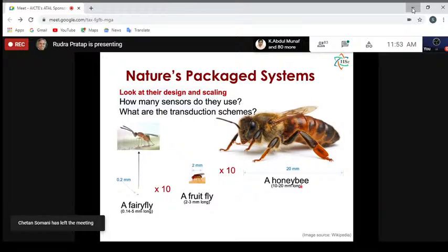On top of that, let's do a photoresist coating. Photoresist, as you know, is a polymeric material. In solution form, you can easily drop it and spin it so that it spreads, right? So you can spin coat the wafer with the photoresist layer.